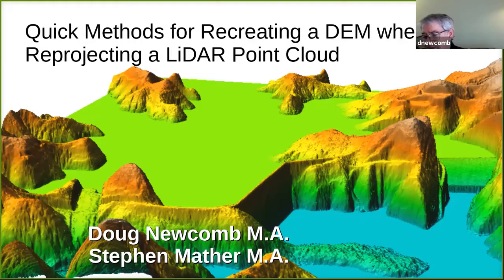Yeah, and I've got some ideas about coming back and doing raster methods for doing the double line drainages. And the other thing you have to watch out for is where you have an impoundment that has a double line drainage flowing into it. I can't see any way around putting in a break line that goes into the raster to clip, so you can cut between the clusters, make 2 clusters instead of 1, so that you're processing the lake separately from the double line. But you've already eliminated so many other manual inputs that seems like barely a nuisance.